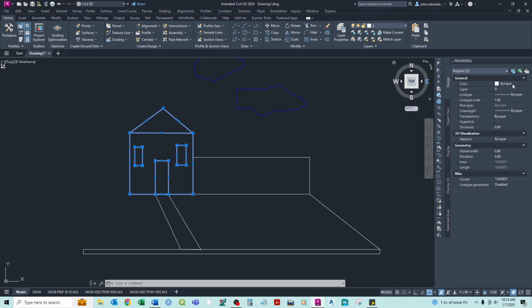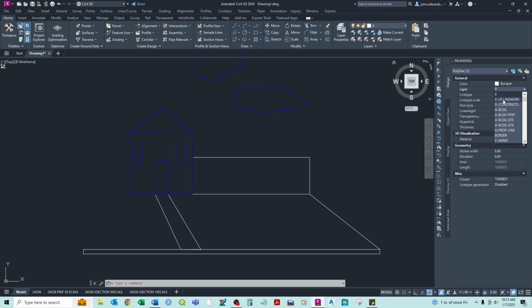But over here, I can manipulate the features of those selected polylines. So if I come to layer, I can hit the drop down, and you'll note now those two I created with the 0 dash are right here and easy to get to, whereas the house layer, now I've got to scroll down. And because there's so many already built in, sometimes it's kind of a pain.